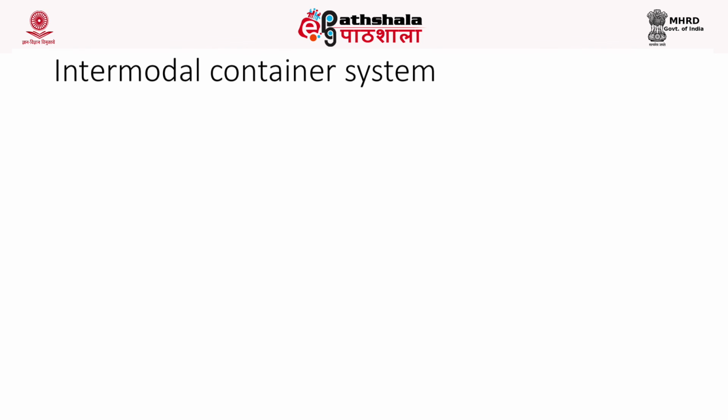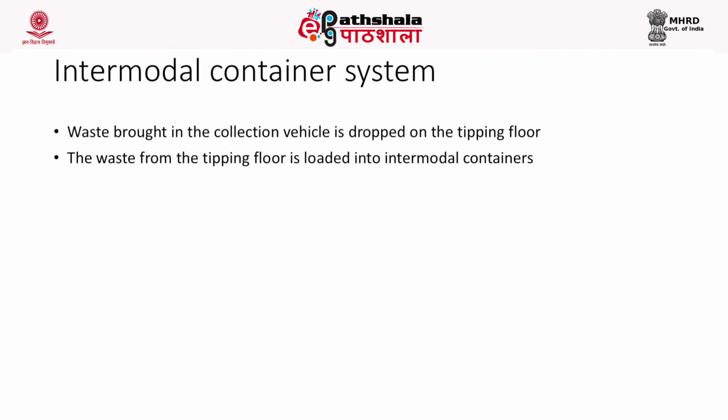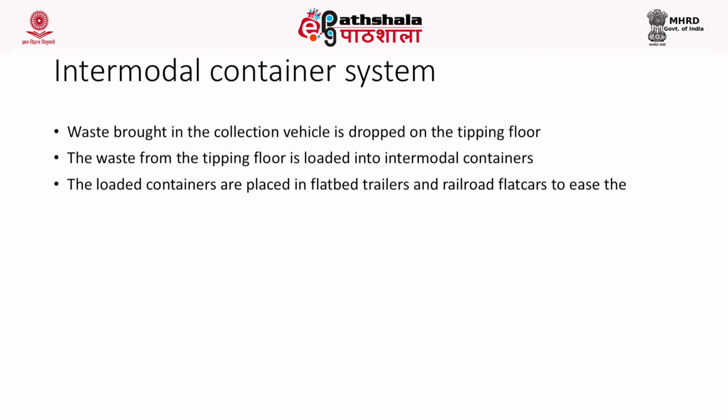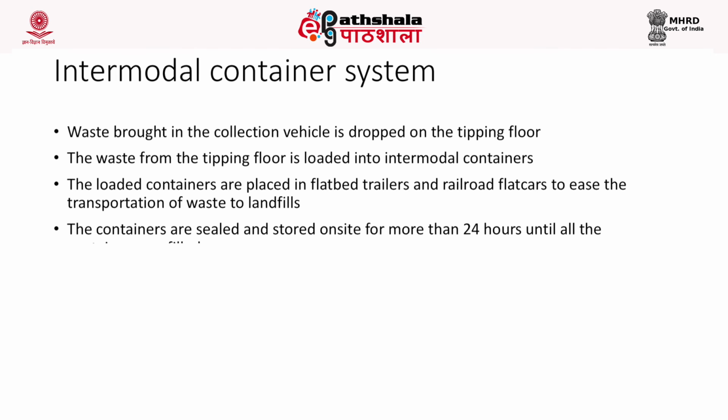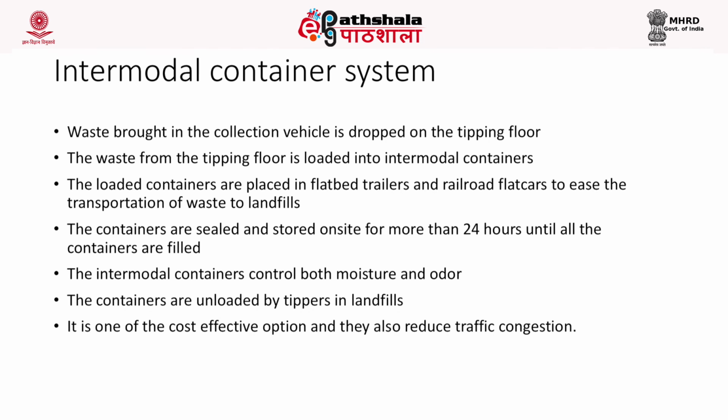The last type of transfer technology is the intermodal container system, where the waste is brought through the collection vehicle, dropped onto the tipping floor, and loaded into intermodal containers. Now the loaded containers are placed in flat bed trailers and railroad flat cars to ease the transportation of waste to landfills.